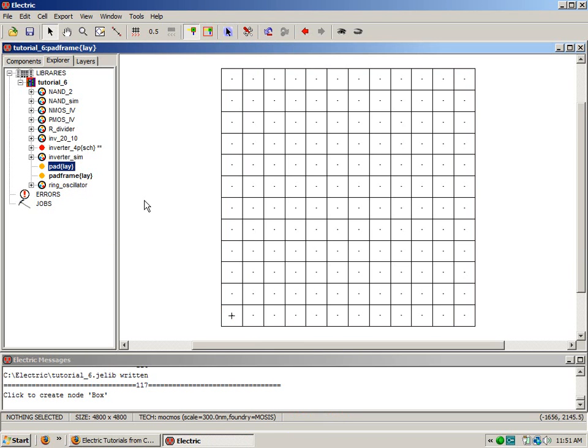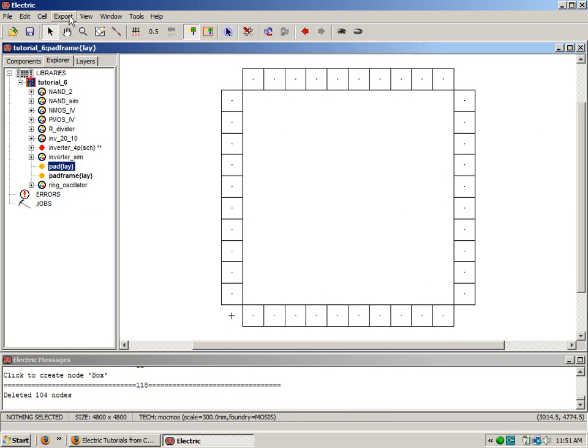And what we need to do is delete everything but the 10 pads on each side. So what I'm going to do, select everything, then press Shift, come over here, then select those. Shift is still held there, there, and there, and hit Delete. And let's save it.